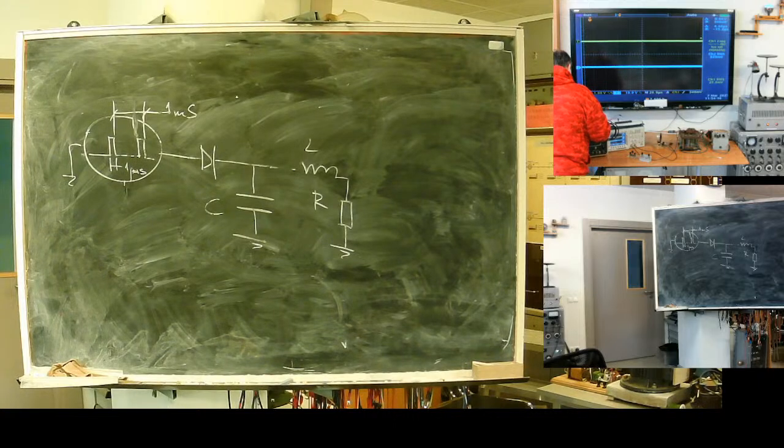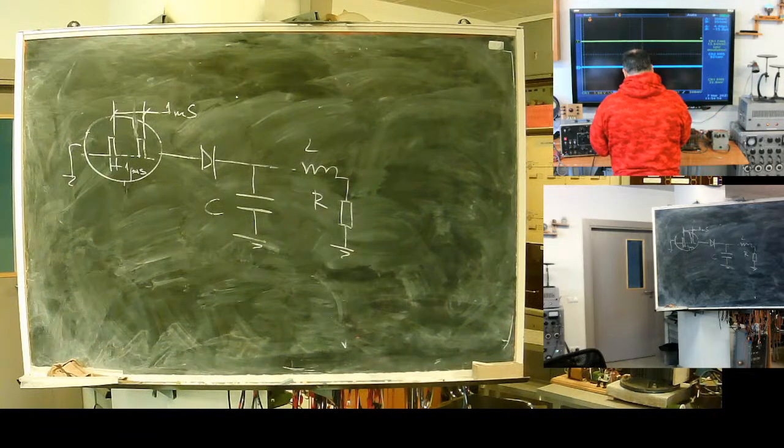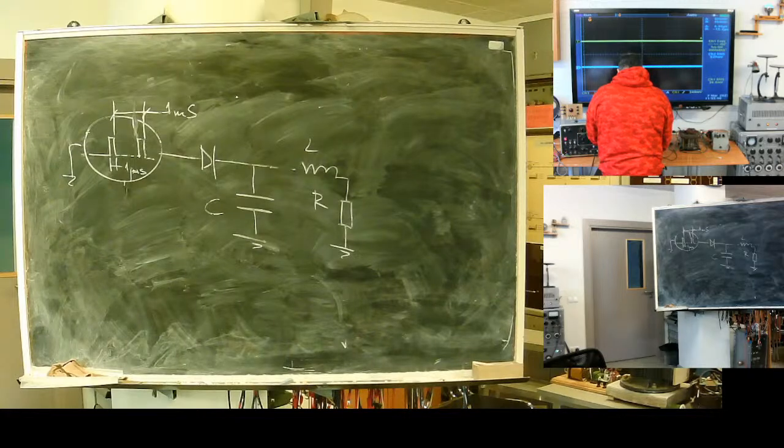With a Q meter, you get overall losses for the capacitor. So if you need to separate losses, at first you measure with the Schering bridge the losses of the dielectric material, and then with the Q meter you get total losses of the capacitor.